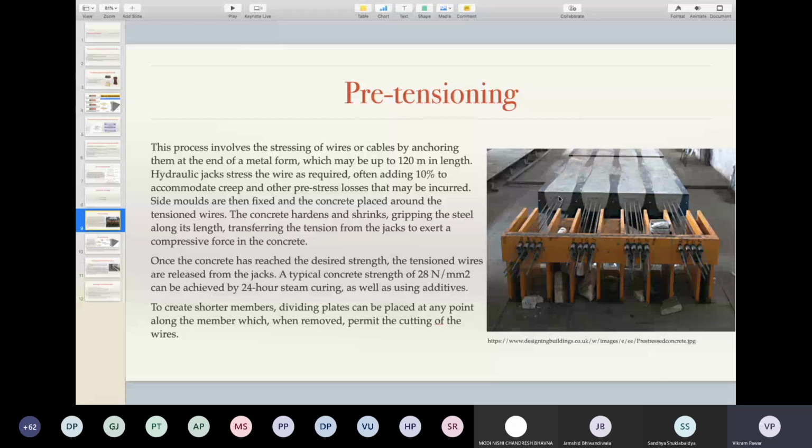Okay, so the whole effort should be towards making the design lean, and towards making the design lean, you got to be very careful about what is the shape. So over here the designers have reduced where the stresses are not required. So they have narrowed the beam in the middle, and they have broadened it at the end. Okay, now this end shows that the steel is already in tension. Now this steel is pulled, they are in tension, the concrete is poured.